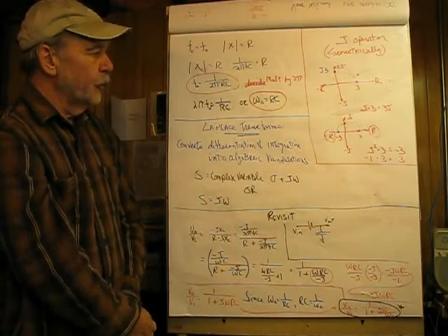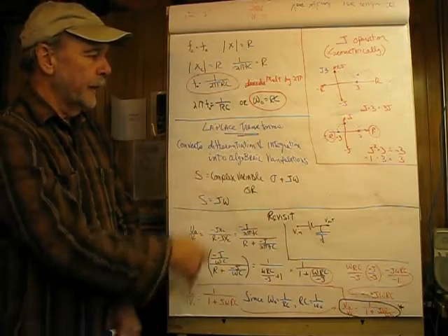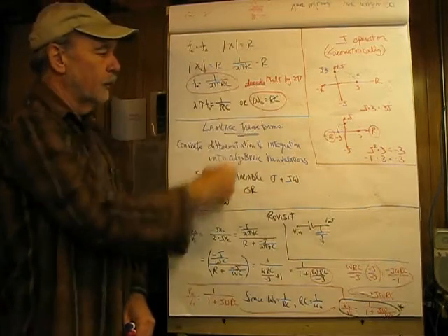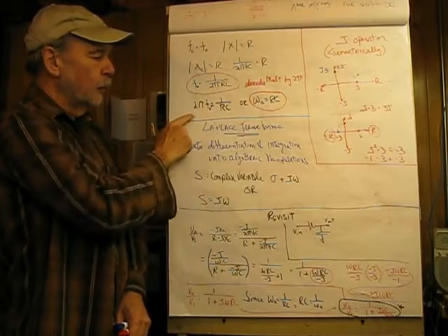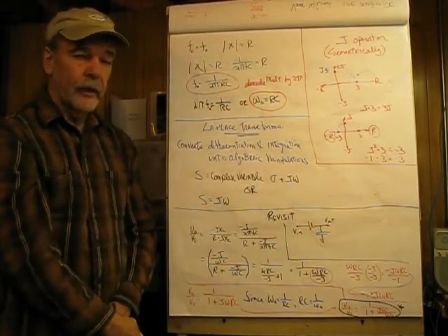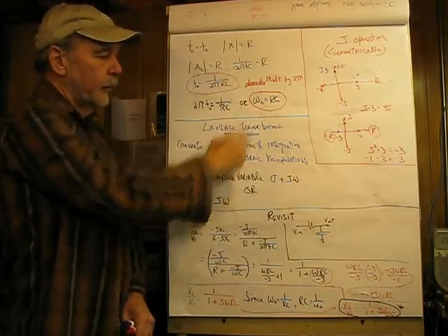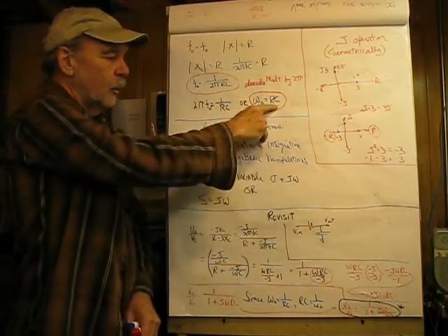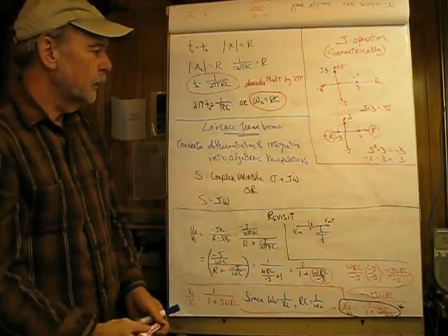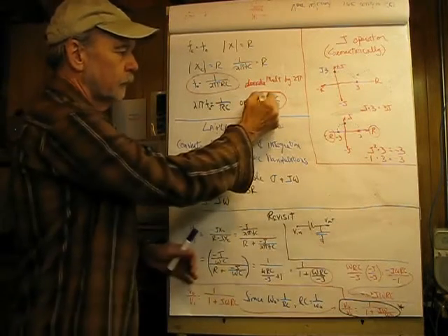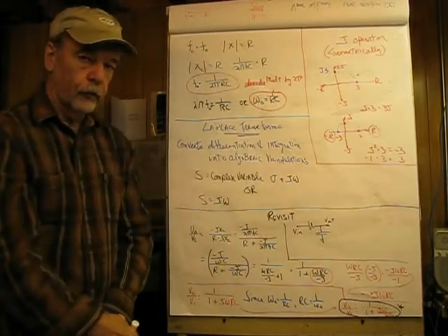So all we have to do in this case is to take our guy here and multiply both sides by 2 pi. And what we get on the left side of the equal sign is 2 pi f, that's omega. Or we could write that as omega 0 equals 1 over RC. All fixed.